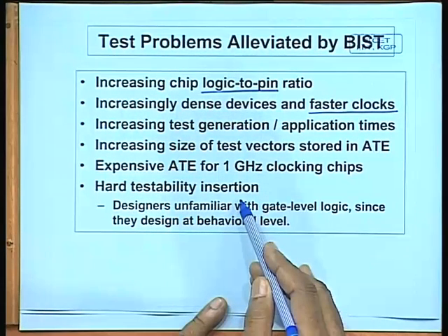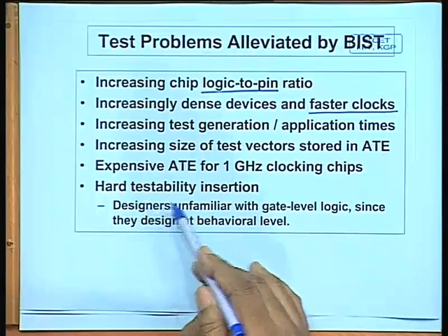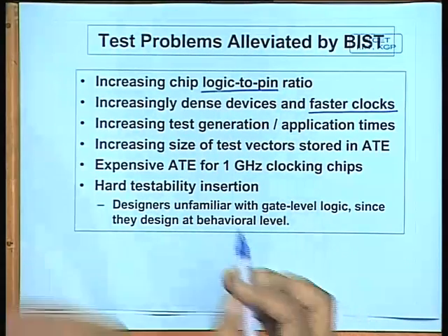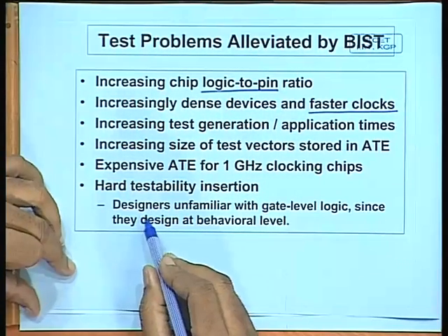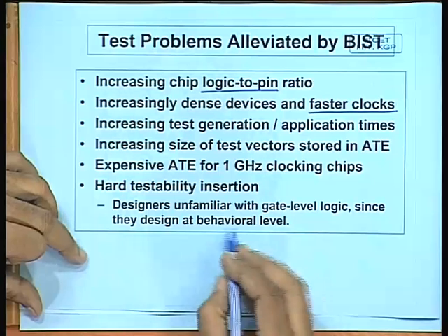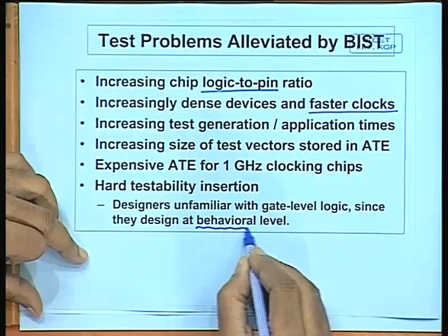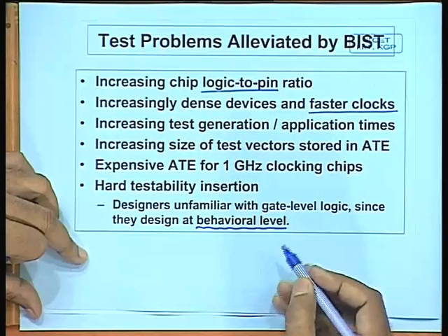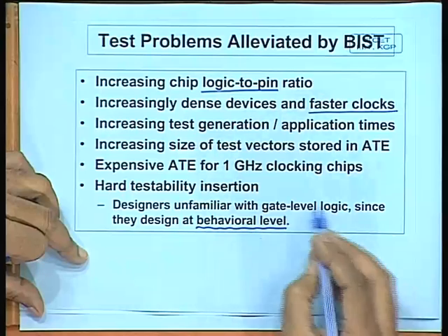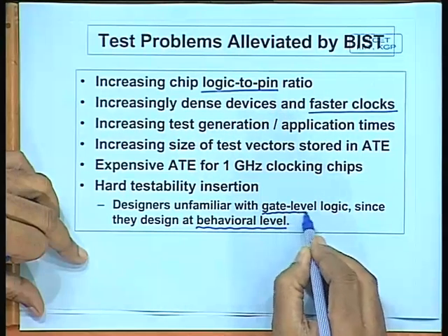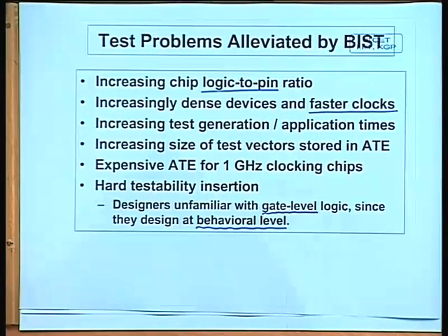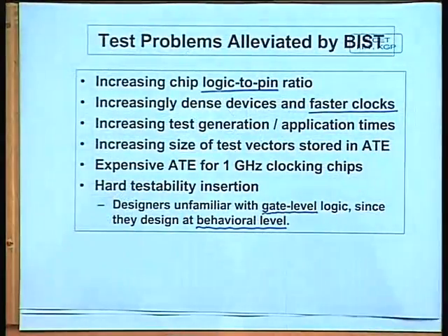Testability insertion with respect to DFT is not always very easy, because designers normally work at the behavioral level. The CAD tools automatically translate the behavioral level into gate level. So, when we talk about inserting testability features at the gate level implementation of the design, it becomes a problem.